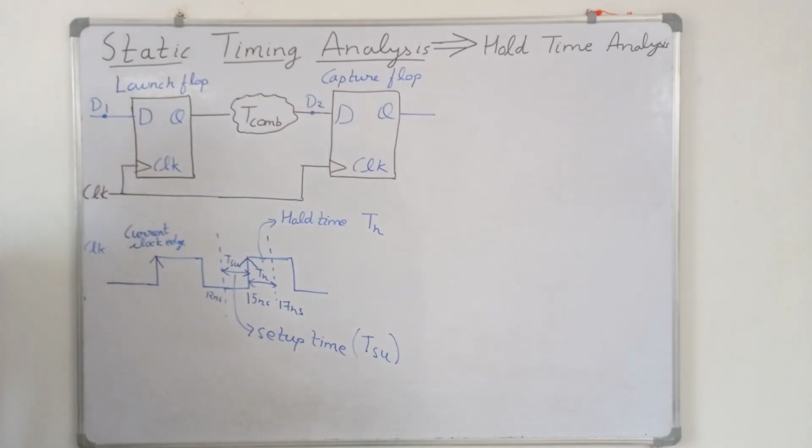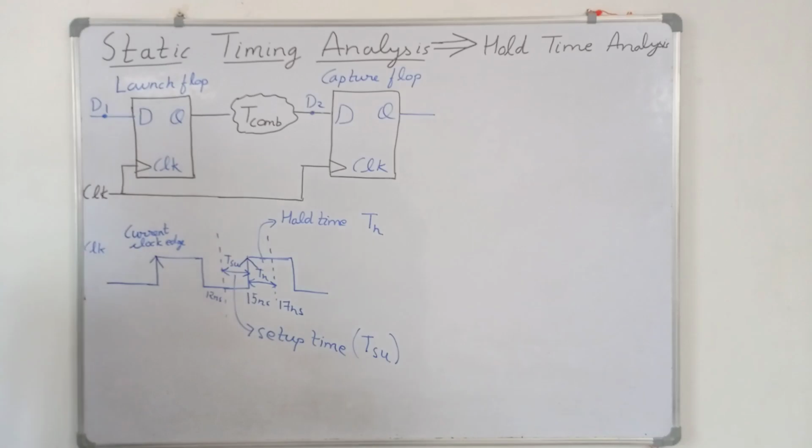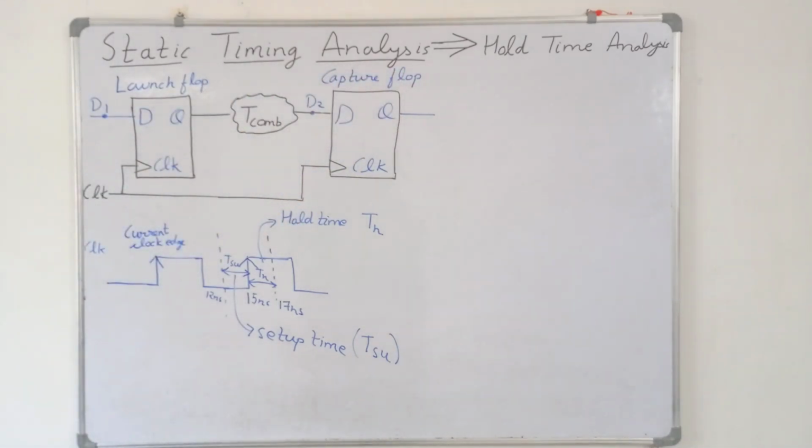So that is why what we want is that the data which is launched by the launch flip-flop at the current clock edge should not arrive at the capture flip-flop before the hold time has passed at the clock edge. So the capture flip-flop can capture the data.